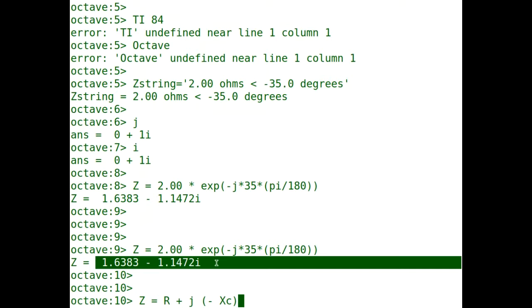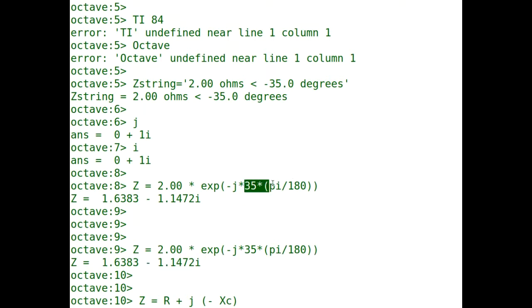Using Pythagorean's theorem, right triangles, we can actually draw the voltages or the currents, and we can calculate the voltages and the currents. We can verify Kirchhoff's voltage law using triangles. We can verify Kirchhoff's current law using triangles. All right, because we have to use triangles because of these phase angles, right? We got 35 degrees here.